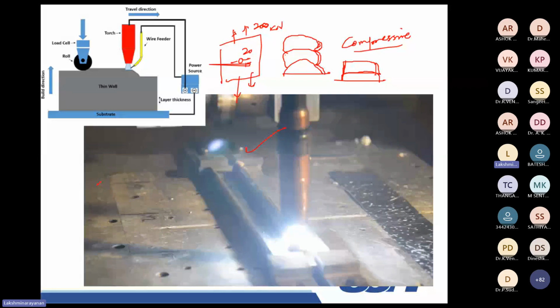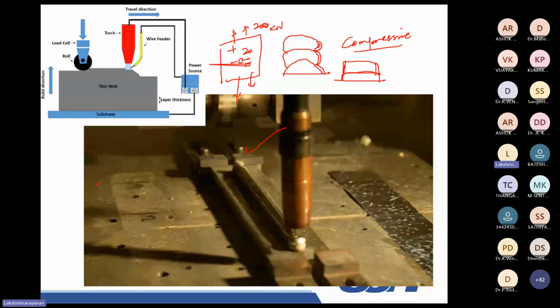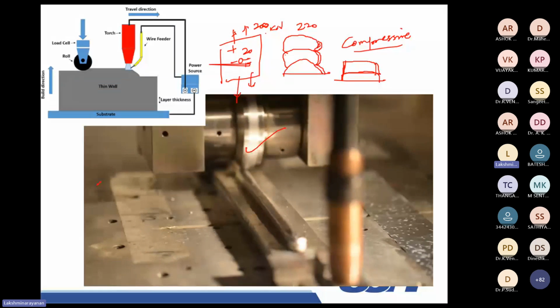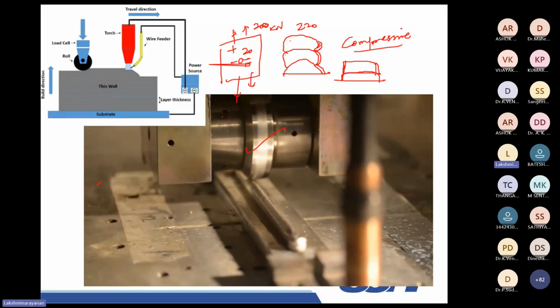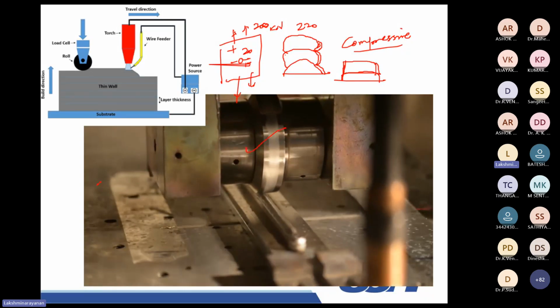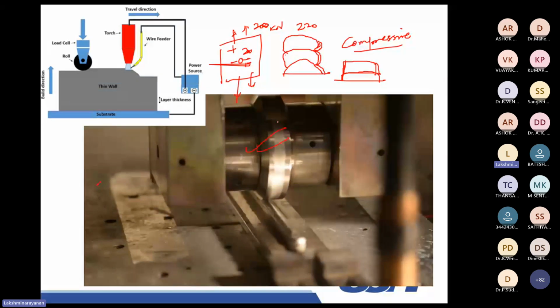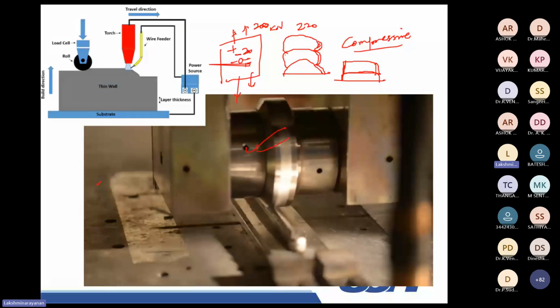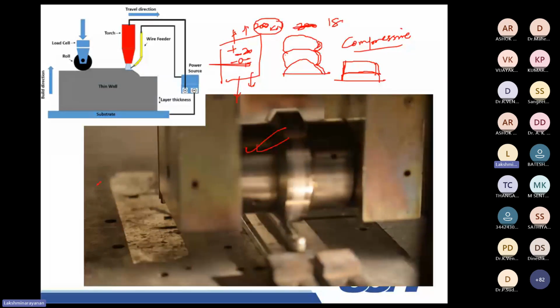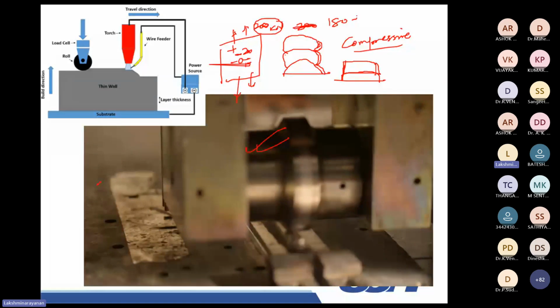That is positive. The actual load applied is 220, not 200, but we think it is 200. We have to take that tensile residual stress into account. So this will help us with compressive residual stress. If it is minus 20, even if you apply 200, it becomes 180. That is the advantage of this process.